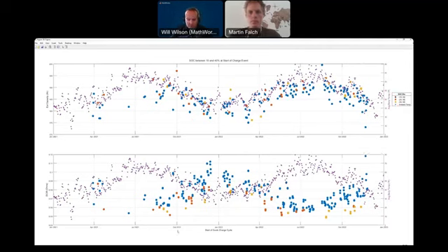If we start with resistance, when the temperature is low, the resistance is high, and when the temperature is high, resistance is low. This is consistent with the physics that we know, how it behaves. So it gives us a sense that our internal resistance calculations have merit. They might not be exactly correct, but at least they're directionally correct and not way off. For the estimated capacity term that we're trying to estimate, we do see some sort of seasonality, that the estimate goes along with or is somehow correlated with temperature. Don't know if that's totally correct. It seems like maybe it's not,